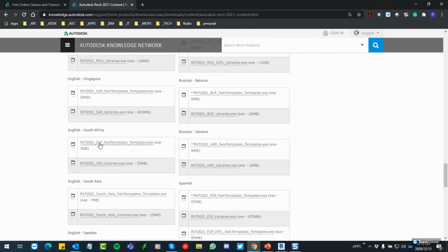So both family templates, if you're not familiar with them, that's how we start families. And then we've got the libraries over here as well. It's the libraries really that contain our rebar shapes, but very specifically in the steel industry, the steel sections that are available for South Africans. It used to be that we used the British shape codes because they were closest to the South African shape codes, but Revit has evolved and they've now got these steel sections for us as well.